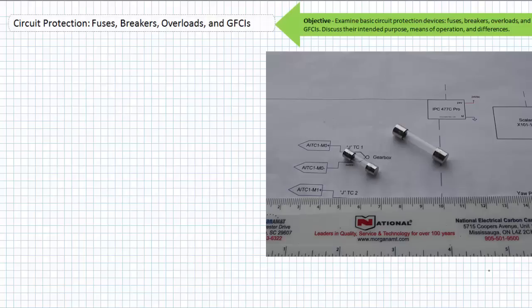The thin wire forming the acting element is representative of the current rating of the fuse. The element inside a fuse designed to blow at 2 amps will be thicker than one designed to blow at 250 milliamperes or 0.25 amps. Again, the transparent housing of these types of fuses makes inspection really easy. You just look at it.